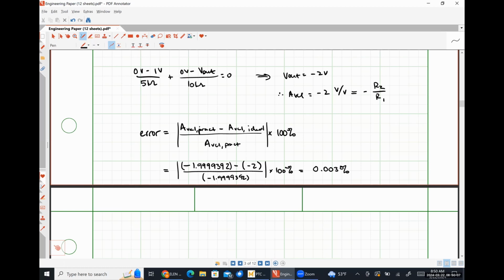In your homework set for this material, I have given you op-amp parameters for effectively just terribly designed op-amps. So input resistance is low, on the order of kiloohms. Output resistance is high, on the order of hundreds of ohms to kiloohms.